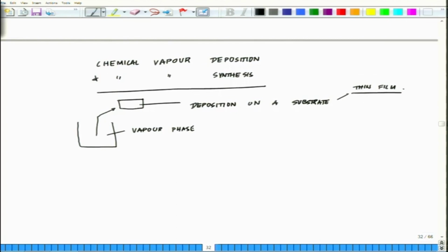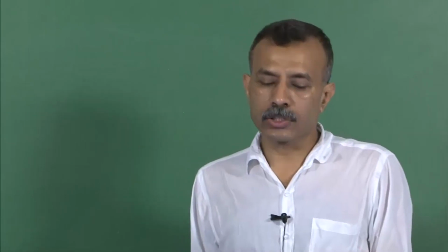Okay. So thin films produced by CVD processes at certain conditions also contain ultrafine particles. Hence, the synthesis of nanomaterial can also be possible by this method if the CVD system is modified. Say for example, you have high temperature in a hot wall reactor, high supersaturation or low residence time and a small substrate. If you have all these parameters and you really want to use a very small amount to synthesize nanomaterial on a substrate, then the best idea is to follow CVD. But the problem with CVD is that it demands a lot of intensive instrumentation, high pressure and vacuum requirements, and several other complex technical know-how is essential for chemical vapor deposition.